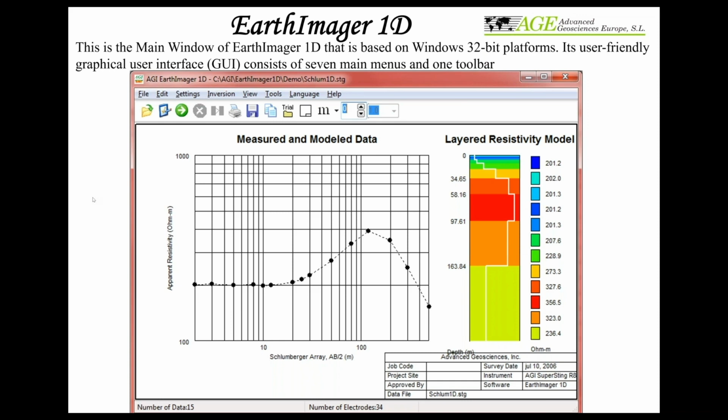That's why, on the edit menu, you want to edit each data point and remove the highly noisy data, maybe a negative apparent resistivity value. Otherwise the averaging will mislead you and you will get wrong or noisy data. So you can do it manually or just edit it.